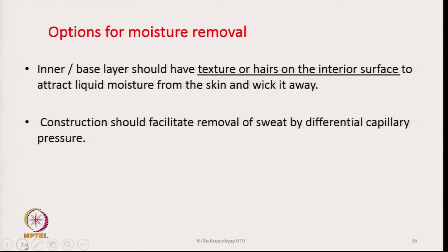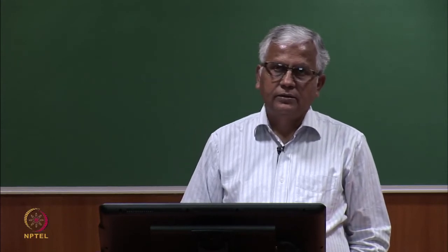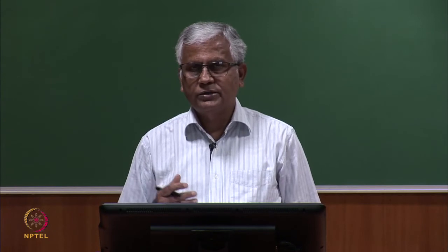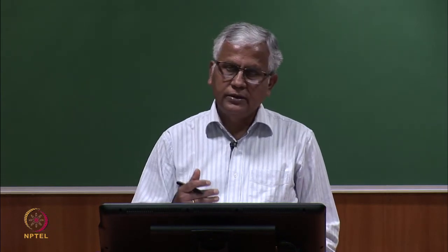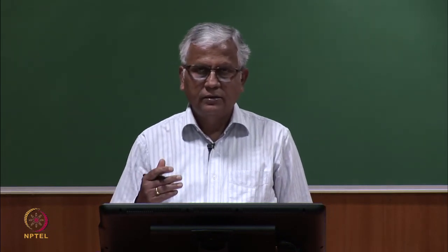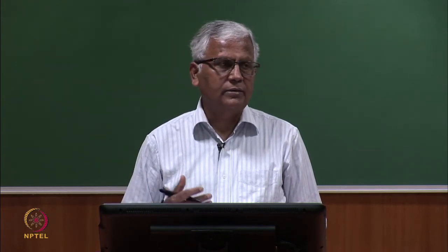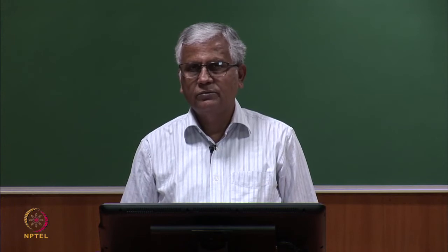Constructions would facilitate removal of sweat by differential capillary pressure. That becomes a very important guideline, that is, how do we take out the moisture from the inner layer to the next layer. The only mechanism that can be employed is capillary pressure, there is nothing else.